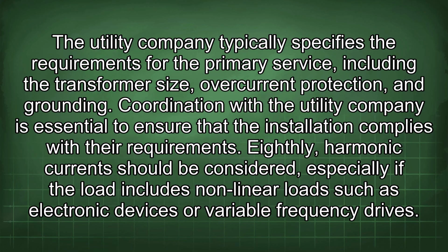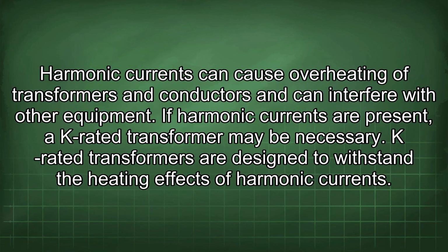Eighthly, harmonic current should be considered, especially if the load includes nonlinear loads such as electronic devices or variable frequency drives. Harmonic currents can cause overheating of transformers and conductors and can interfere with other equipment. If harmonic currents are present, a K-rated transformer may be necessary.